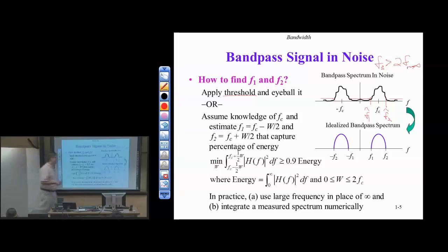And I'll just tell you the punchline. The punchline is that the sampling rate just has to be greater than the bandwidth, F2 minus F1, which is much smaller than 2 times F2. We'll get to that later in lecture 4 slides. But for now, if we're going to plot this in MATLAB, we want to go with 2 times F max.